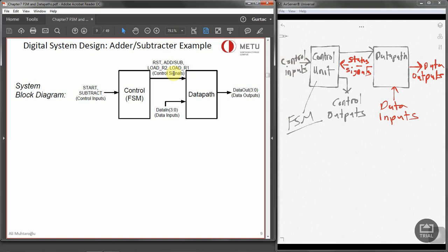So when we do this kind of design, we normally want a register transfer operation to occur not with every clock cycle, but only under predetermined conditions. So what we can say is, for example, if T1 equals 1, then R1 is going to be R2. So this is a condition. So not just with the clock that we are going through the cycles, but we have some predetermined conditions over there.